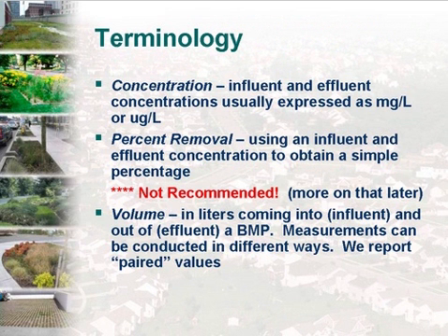So just moving on here, a little bit on terminology, just so that we're all on the same page again, and I know most of you probably know this already. We are going to be talking about concentrations, and concentrations have their place in our discussions and are very useful. Usually we show those as milligrams per liter or micrograms per liter. So those are things that you're going to see labeled on some of the charts that are coming up. Percent removal is another thing that's commonly seen out there in literature or brochures and things like that. And we're going to show you in a minute why that's not a very good measure. But basically, you're taking an influent and an effluent concentration, and you're coming up with a simple percentage. And that percentage can often be kind of misleading. So we'll show you that in a minute.